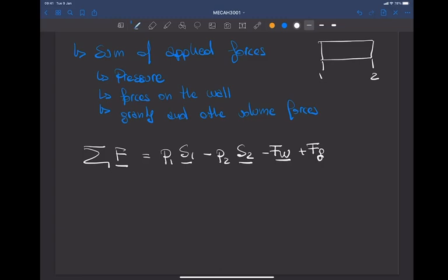You see the fluid that is entering the control volume here is exerting a work to enter the control volume. So it's exerting a work on the fluid which is in the control volume, and so this contribution is positive. For the pressure contribution on the outlet, this is done by the system on the outside of the system, and so this is a negative contribution.